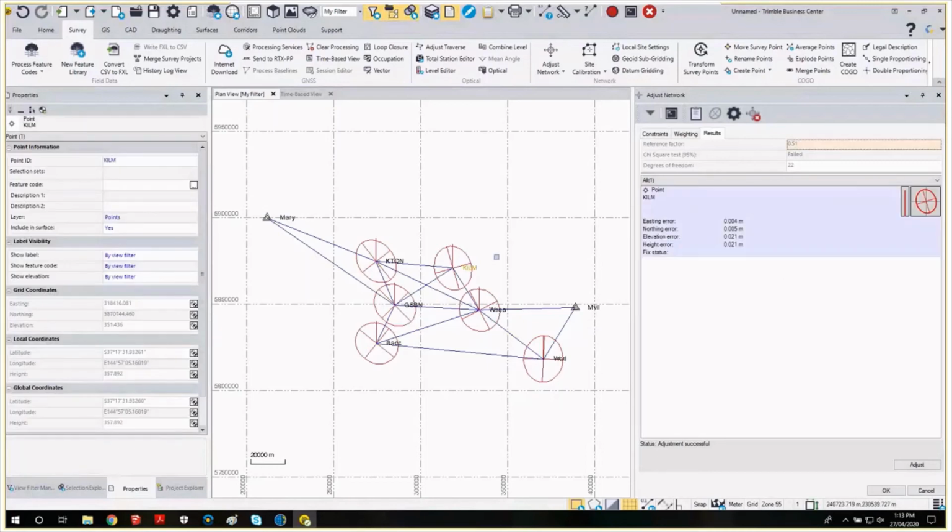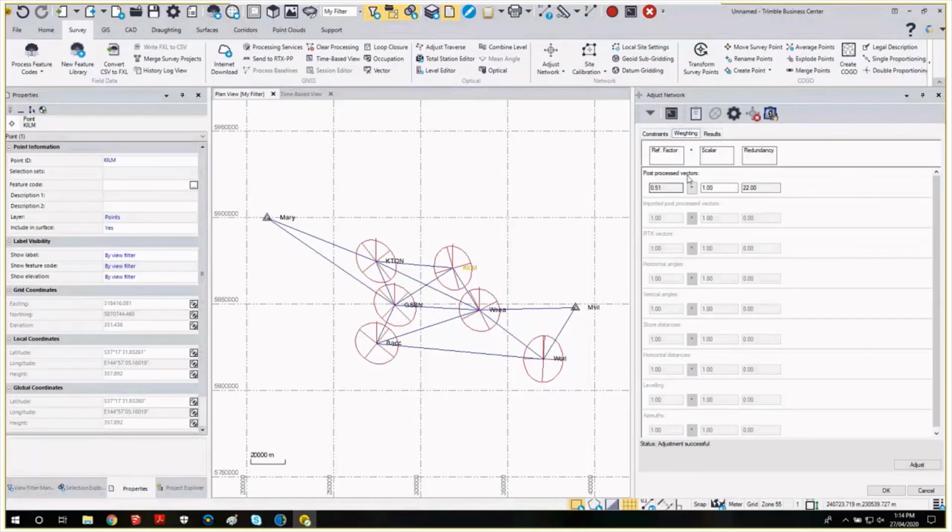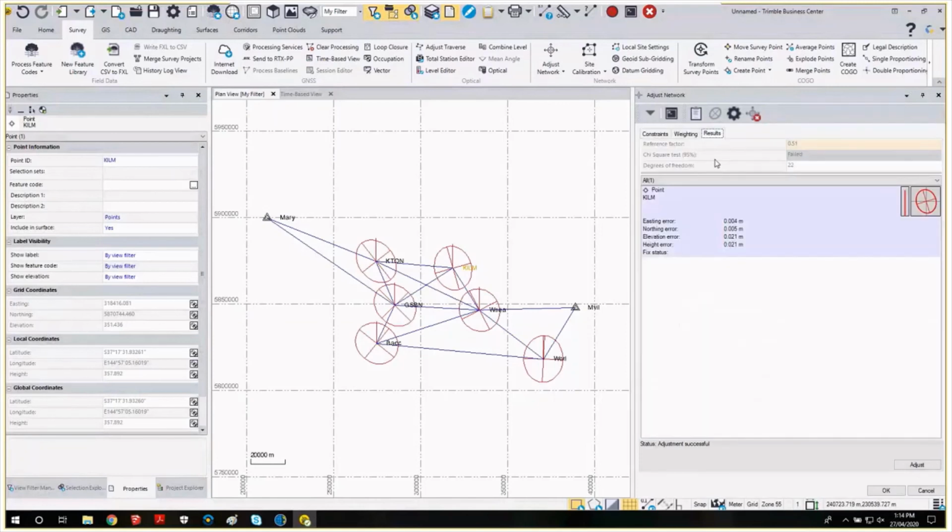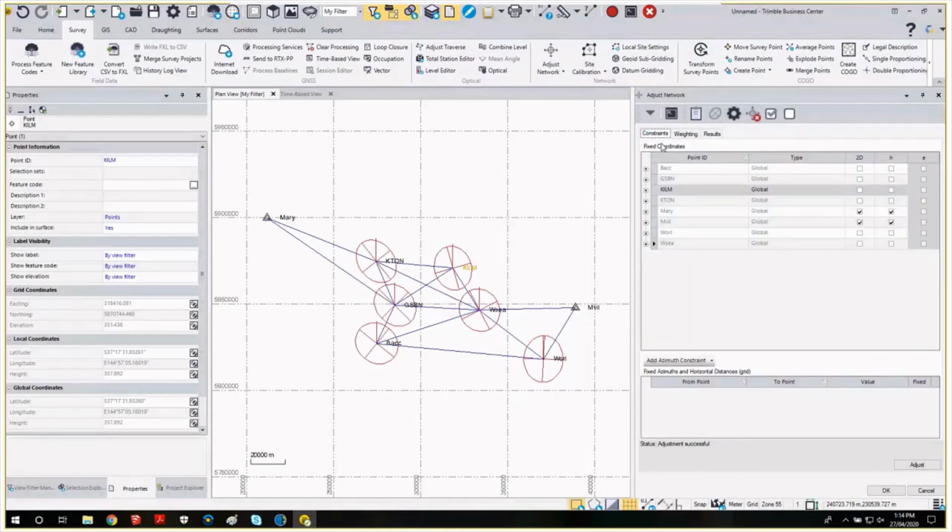If we have a look at normal, we'll see we're getting east, north, and elevation. These errors have increased slightly because now we're not distributing the error across these points out to the ends as well. We're now only able to distribute our error within what we'll call our network. So we haven't seen anything major pop up here in terms of blunders at the moment.